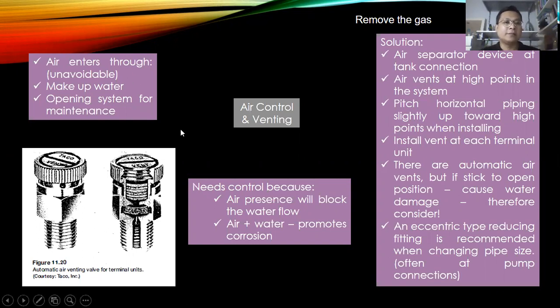A higher amount of trapped air will also create corrosion. So the solution is to remove the gas with a separation device at the tank connection.